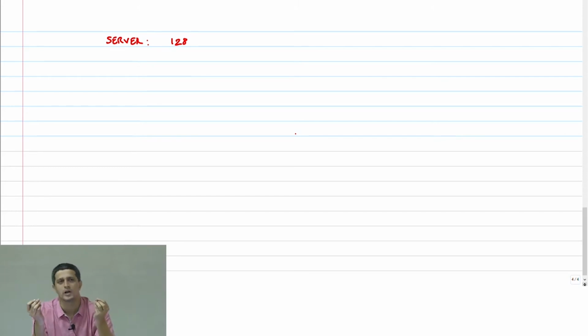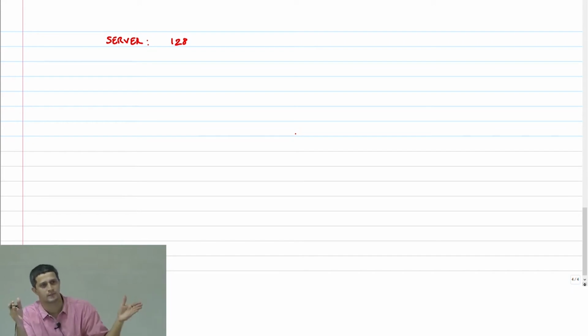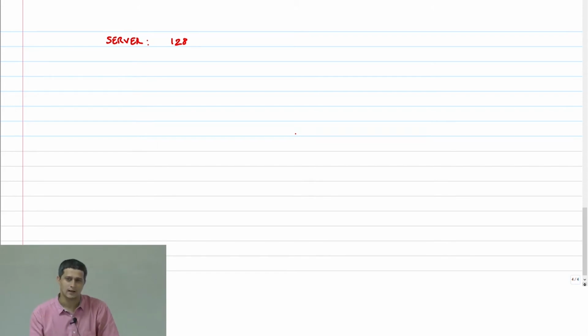So there's only a certain amount that you should spend optimizing the circuit part of a full adder. Beyond that point, even a desktop machine is 32 bits, right? Now even that's 64 bits, right? GPUs, all of these are going to have larger bit registers. And in order to optimize that ripple carry delay, we have to optimize the architecture of addition. It's not possible to do it through circuit optimization anymore. Okay. So we will look at various architectures of adders going forward, and some of them we will cover in this class. Okay. So the first thing is called a